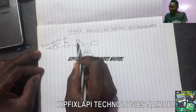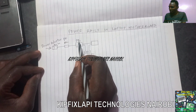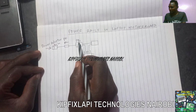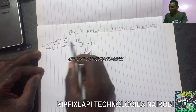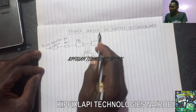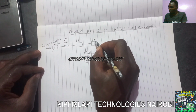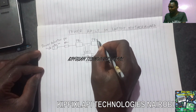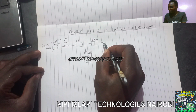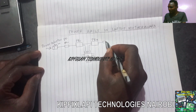If you find a component written BQ, it's a power MOSFET. So in short, the Q represents MOSFET. In my last video, I explained what the L means. That's an inductor. F is for fuse. Q is for MOSFET. So this is MOSFET 1, and this one is MOSFET 2. We say MOSFET 2 is called the supply MOSFET because it supplies power into the motherboard.